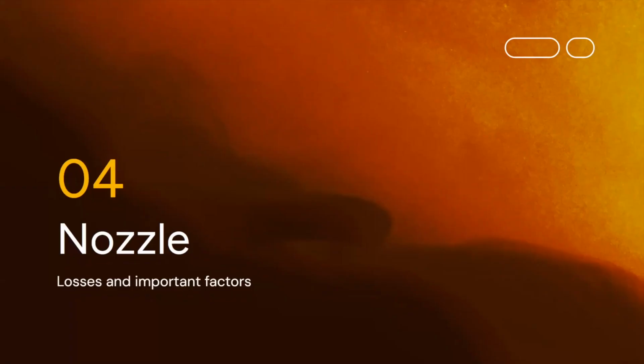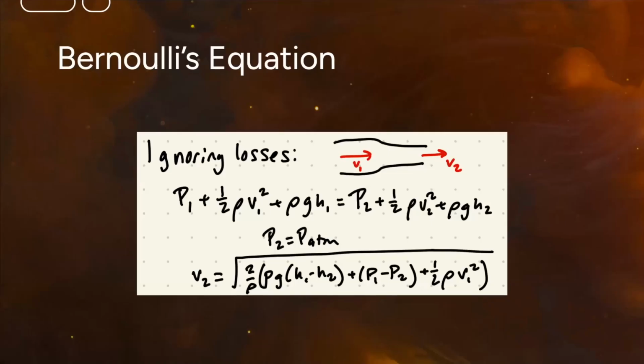The nozzle is shaped to minimize the losses while achieving the target velocity of the stream as it exits the sprinkler. And after exiting, the water pushes the deflector plate, which in turn pushes the sprinkler arm connected to the spring that turns the sprinkler. The nozzle also lowers the pressure of the water by constricting the diameter of the pipe to atmospheric pressure and increases the velocity through the Euler equations, which you can also see with Bernoulli's equation here because it is an incompressible flow.